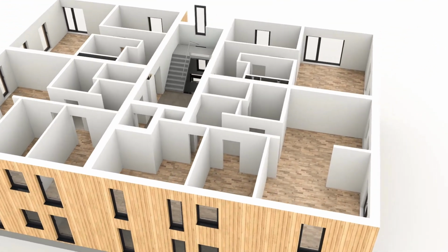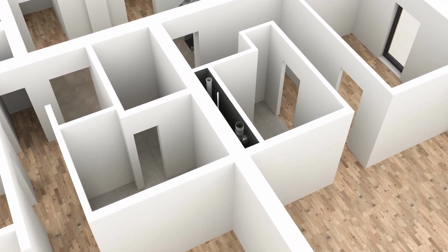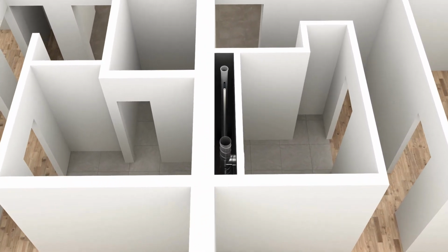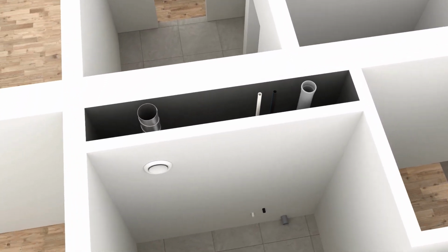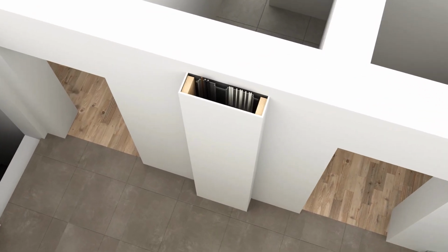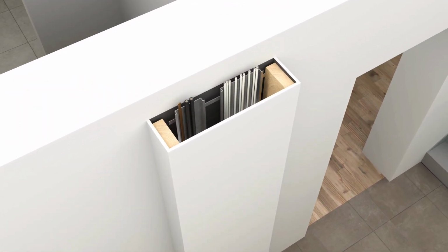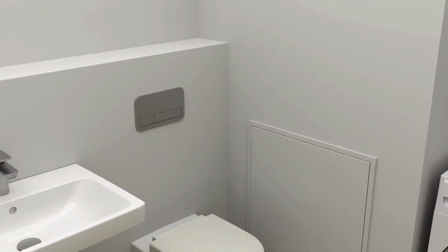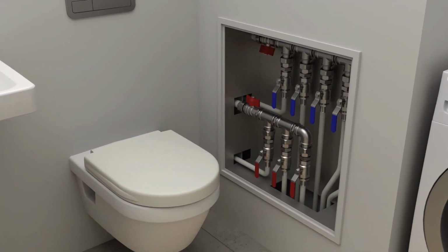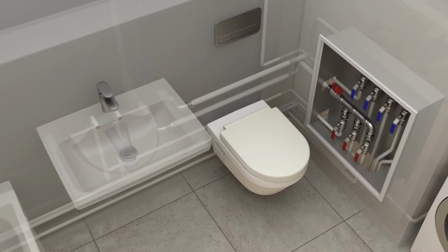Multi-story buildings use communication shafts for heating pipes for domestic water and water heating, as well as ventilation and sewerage pipes and electrical cables. Depending on the type of building, it may be required that electrical cables be located in a separate shaft. Through the shafts, water pipes run into water or heating collector cabinets. From there, water is distributed to the intended fixtures, like sinks or toilets.